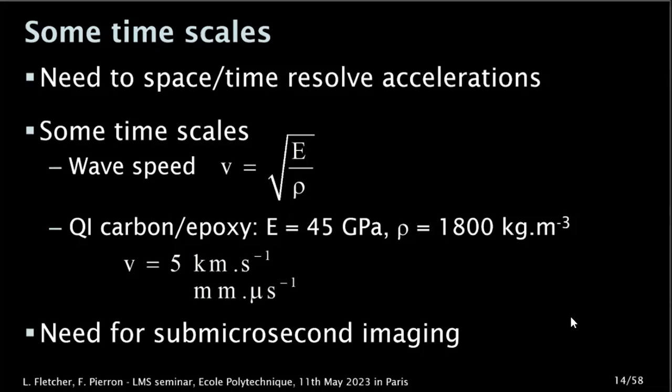And you need to do it in a way that you have enough pixels, so you also have spatial information. Until the recent past, this was not possible with enough image quality to do quantitative imaging. If you look at the rotating mirror cameras, for instance, like the Cordin cameras, it is very, very hard to make precise measurements with these, certainly not in the elastic range. If you look at gated intensified cameras, it's the same thing, too much blurring caused by the image intensifiers.